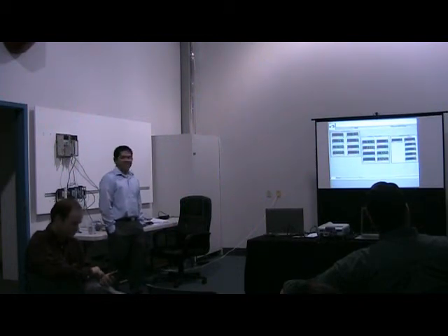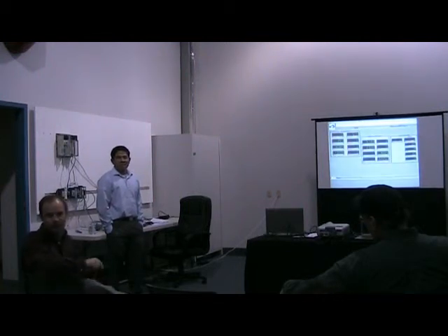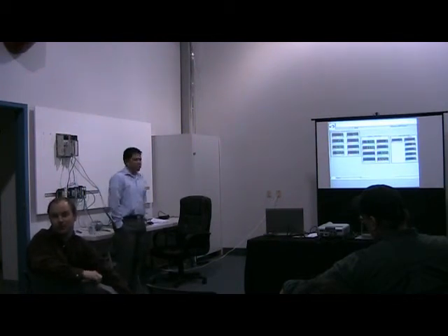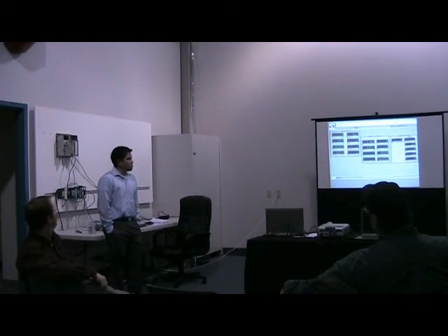Yeah, it's probably handy to know your transmitter temperature, like at City of Las Vegas, or anybody's transmitters, if they're only rated to 120 Fahrenheit, and your transmitter's in direct sunlight and it's actually cooking up to 130, 140, that would be good to know. Absolutely, another great use of HART data. Or it could be misinforming you as well, outside of operating design spec. Exactly, and therefore misinforming you.